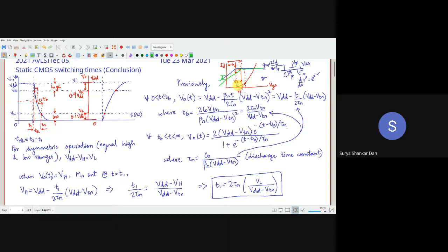Okay. So if you are making it like a 3-hour movie, what will happen? Your laptop is becoming hotter. Your IC is becoming hotter. What will happen? Your threshold voltage will keep on decreasing slightly. So after 2 hours, what will happen? Your threshold voltage has come here. So what will be the leakage current? It will come here and like that. So the leakages will become very high.